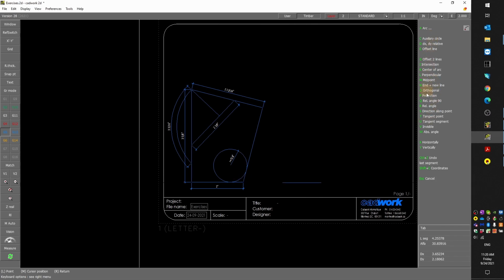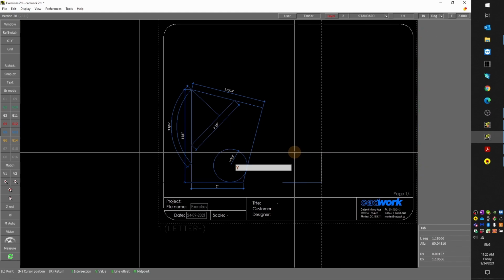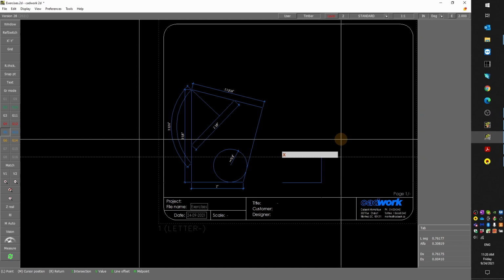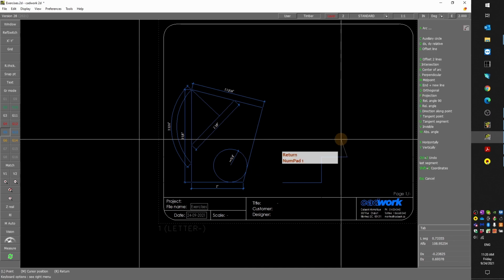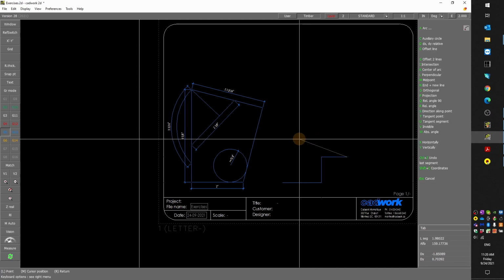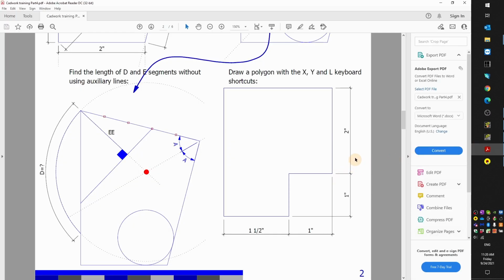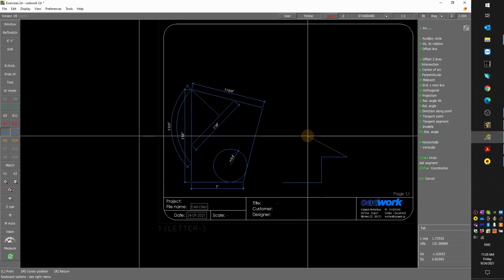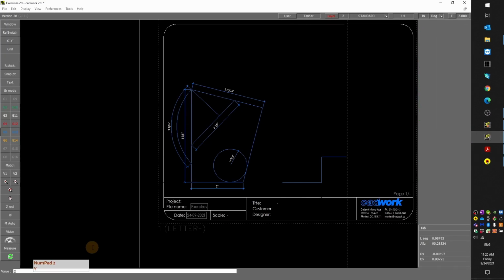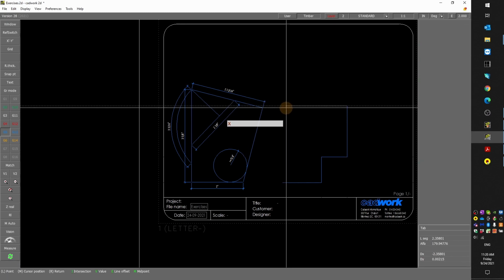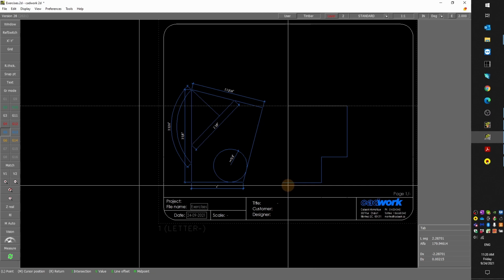So you see again, you have shortcuts down here. 1 inch. In X, an extra 1 inch. So positive. I could go in the negative direction as well. And then I need to go 2 inches up. So vertically in Y, 2, and then X. So back in X, I don't need to do the math.